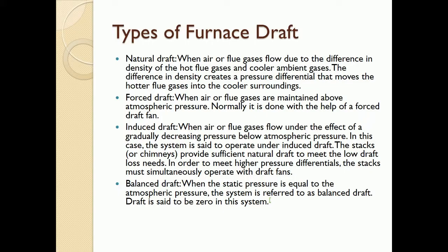3. Induced draft, when air or flue gases flow under the effect of a gradually decreasing pressure below atmospheric pressure. In this case, the system is said to operate under induced draft. The stacks or chimneys provide sufficient natural draft to meet the low draft loss needs.